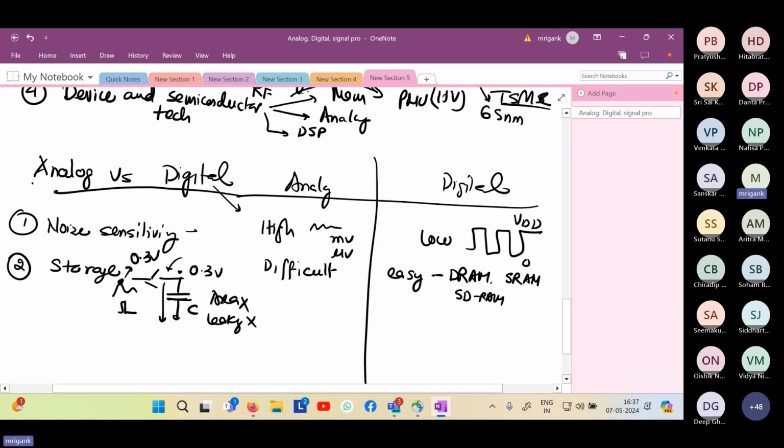So latches, at least you have studied. Latch circuits, any NAND latch or NOR latch? Those circuits are ultimately like memory. With the NAND latch, if you disconnect it from the input, the inputs are set to 0, 0, it will retain whatever output was there. It will not discharge. Whatever you set it to, 0 or VDD, the output will remain like that. So latches are an example of memory. Ultimately, all these SRAM bit cells are something like latches only. We will discuss that.